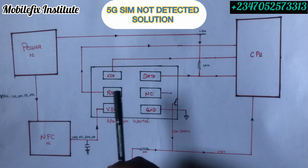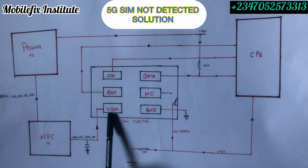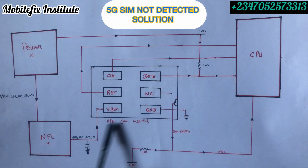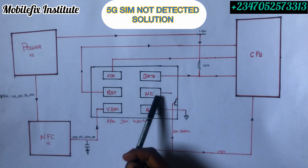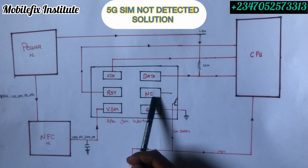This SIM tray port normally has 6 pins: clock, reset, vSIM or VIO, data, NC, and ground. This NC stands for not connected. So on this pin, you won't get any readings because it's not connected.